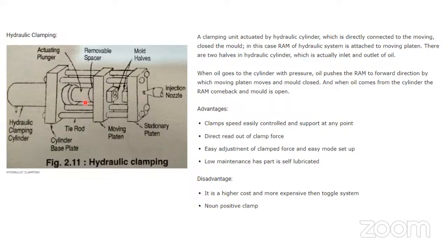Now, how can you measure the clamping pressure here? Just by putting a pressure gauge here. Put the pressure gauge here, and how much force the oil applies, you will get here only, right? Therefore, clamping force we can measure here in this case because it is the direct, completely parallel force, so you can measure at what speed the oil is passing inside, right? Therefore, here we can measure the clamping force. This is the only machine where we can measure the clamping force.